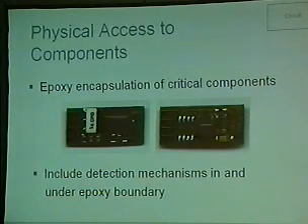But on the other side, there's a serial EEPROM that's covered in epoxy. But then there's those 8 silver pads, which is an expansion memory footprint that isn't protected. The nature of the serial EEPROMs will allow me to attach probes to the 8 unprotected pads and read all of the memory of that protected device. So there's epoxy coating on there to prevent me from touching that device, but I can still read all of the data in it. And that led to compromise of the device and also led to a security advisory.